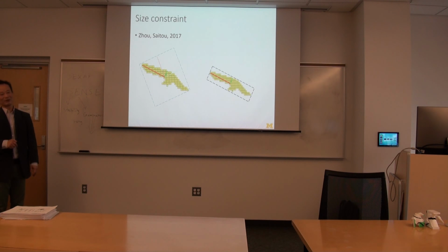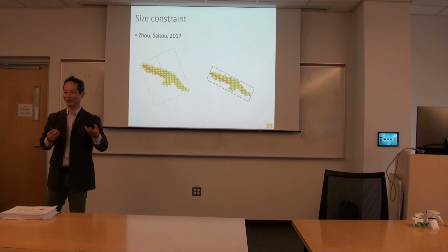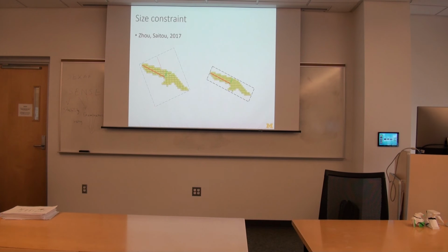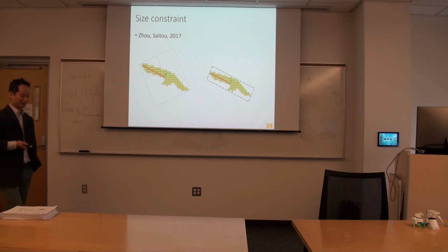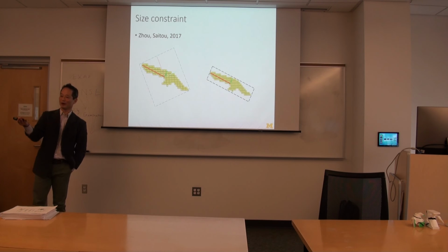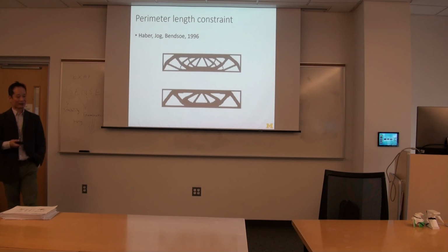Okay, and so we view the cloud as a point cloud, basically, and then figure out the major and minor axis, and then close the bound. Approximately, using a continuous relaxation of the max-min function, of course, which they call the Heaviside relaxation. But indeed, what we did was figure out the right orientation to look at by PCA, and measure the maximum and the minimum distance of the point cloud, weighted according to the value of the field value of rho. So size is done.